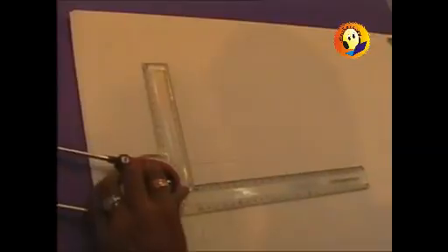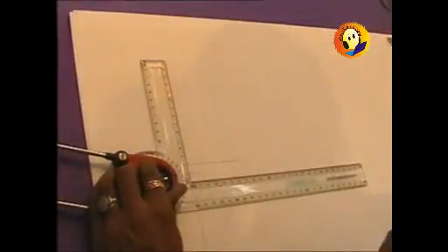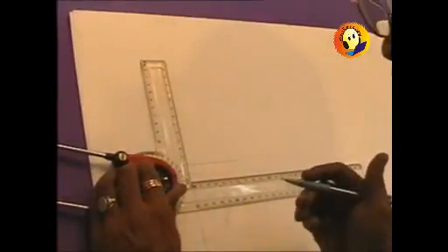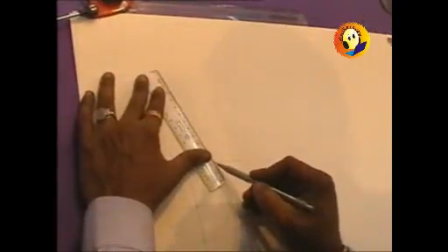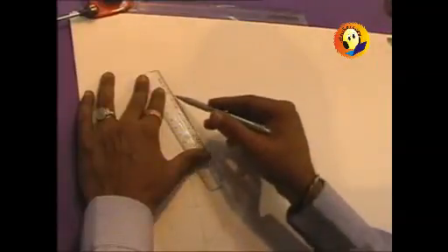Now all the points of this hexagon should be taken up and they will be forming the base. The height of the hexagonal pyramid is not given to us. Let us take that height as, say, 90 millimeters. So measure 90 millimeters in the front view. And as we get the vertex point in the elevation, join all the corners of the base to the vertex.